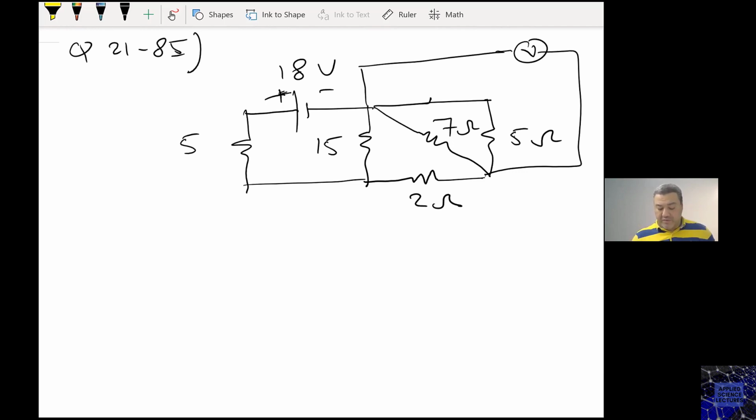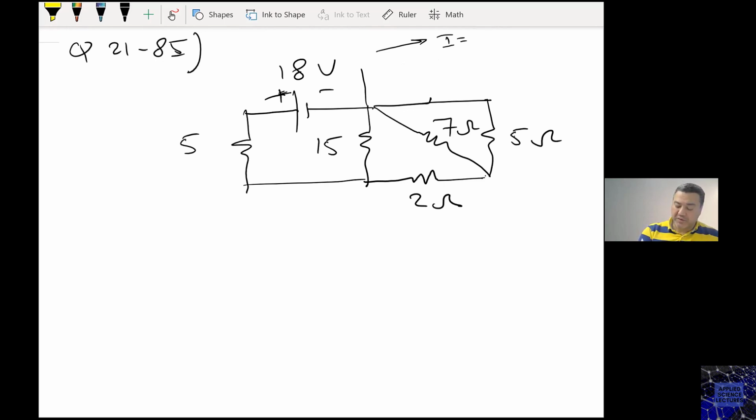So how can we calculate the readings for the voltmeters? Number one, those voltmeters are ideal, which means the current going into the voltmeter will be zero. This voltmeter is not going to consume anything from my circuit and should be treated as an open circuit. Its only purpose is to measure the potential difference between those 2 points, so I can remove this voltmeter and substitute it with the potential difference I'm interested in, which I'm calling delta V1 between those 2 points. It's only an indicator of where I should be calculating the potential difference.